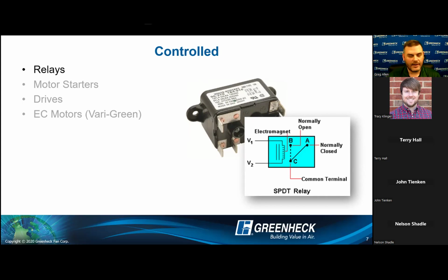You can get relays in so many different ways. Most of the electricians that I know have a box of these in their vans, and they're creating a kind of mechanical logic using them. They can do amazing things with them. But in the end, you have single pole single throw, single pole double throw, double pole double throw. There are a lot of different types of relays.